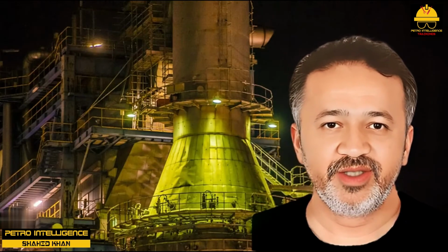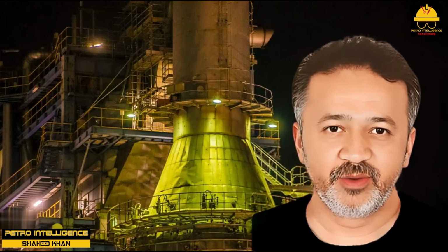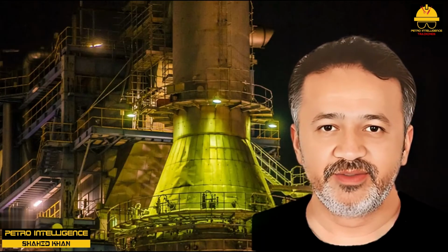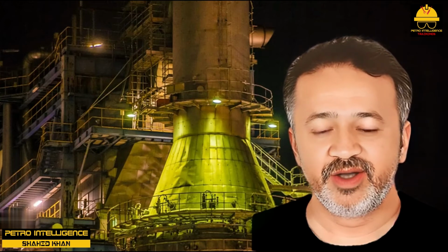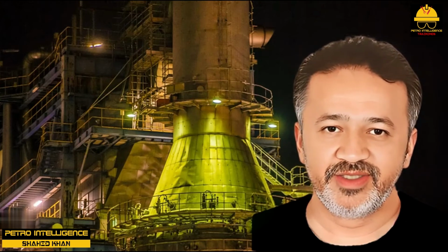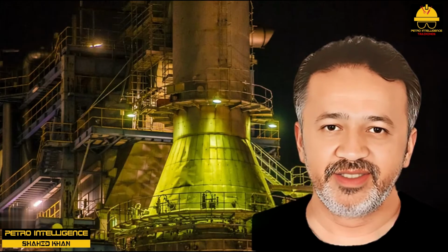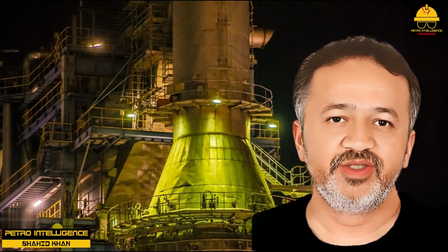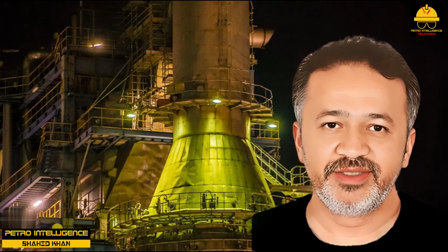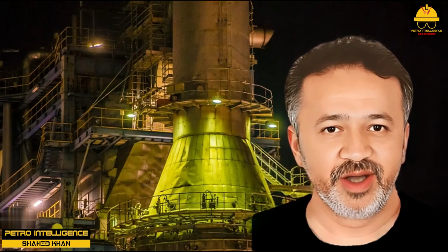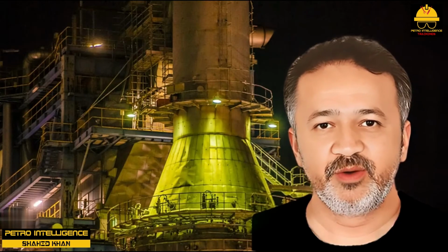The search for the correct combustion air rate on any particular day is known as heat-proving the heater. Experienced operators will increase and decrease the combustion air to find that particular rate that minimizes the fuel rate. Naturally, experienced operators have been heat-proving heaters since long before oxygen analyzers were invented. In view of this, it seems that we do not actually need an oxygen analyzer to run a piece of fired equipment efficiently. The concept is not to run the fired equipment to a specific oxygen target, because the oxygen content corresponding to the most efficient operation varies, but to aim instead to maximize heat absorption to the process stream for a given fuel rate.